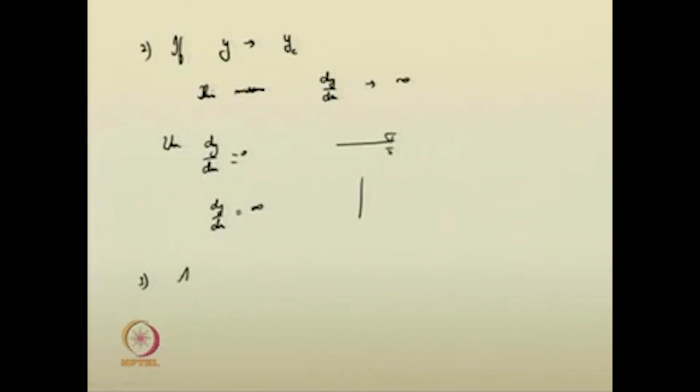Now, what happens at large depths of y? At large depths of y, that is y tends to infinity, your dy by dx tends to become equal to the bed slope S0, and the surface is also approximately horizontal. So, at large depths of y, you can note that your dy by dx is almost the same as the bed slope.